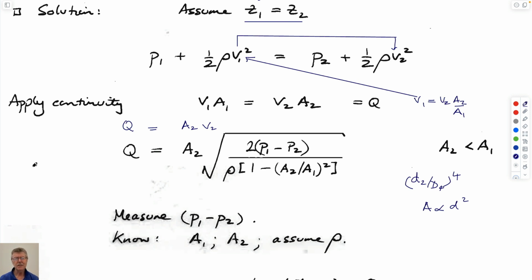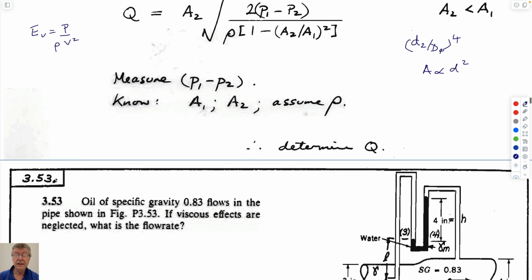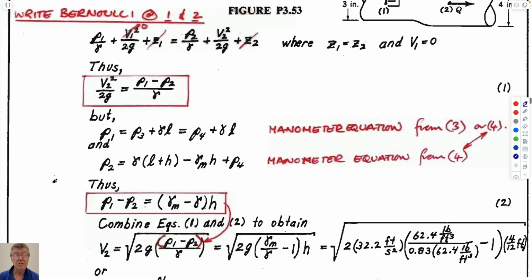Was that one of the questions on the test? No, I guess it was Reynolds' number on the test. Eu is just the pressure divided by rho times V squared. I think you were asked what the dimensions of that were. So this is the velocity of the fluid that hits you in the chest. This is the pressure that is on your chest. And if it's water with a high density, it hits you harder. We can use this number to get the force that's applied. Okay? So that's Venturi flumes.